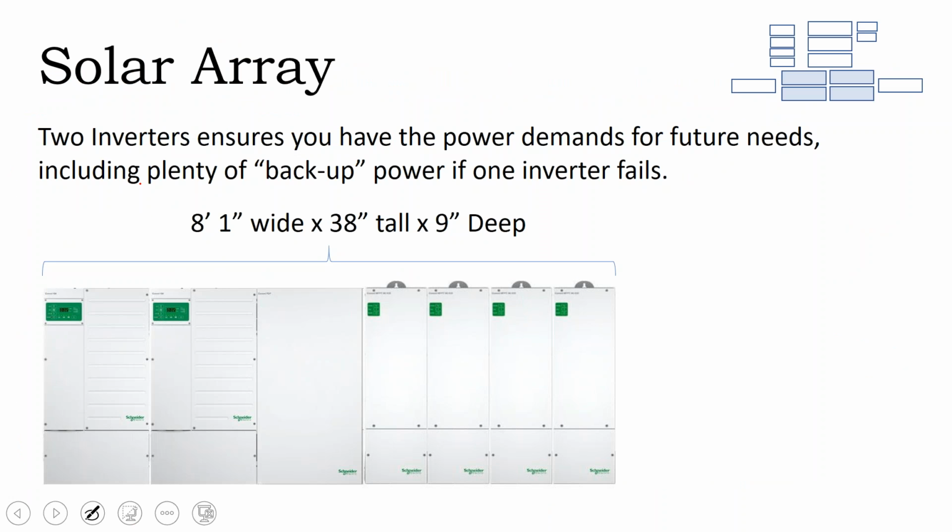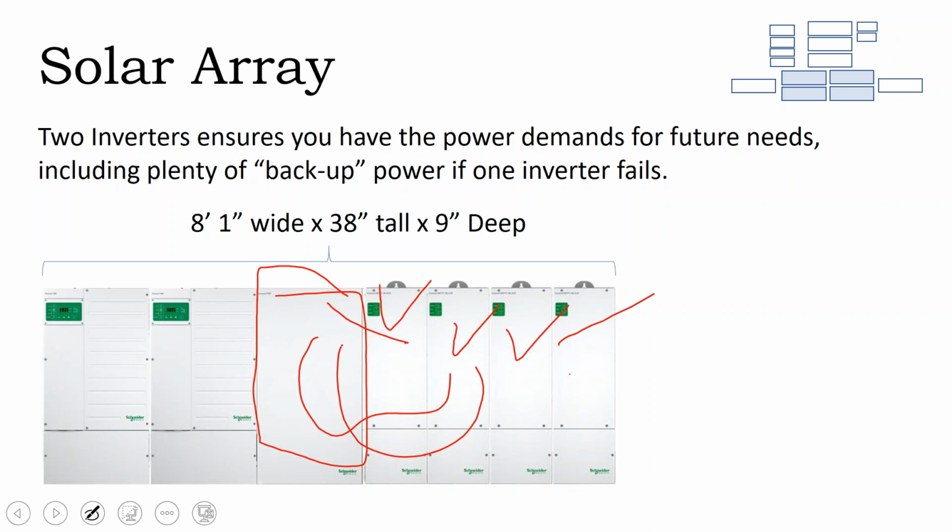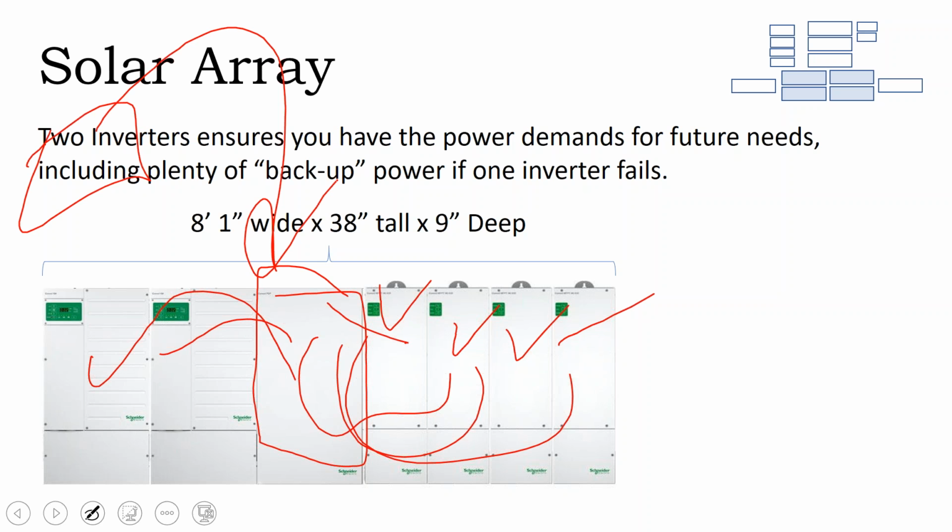This is our inverter system. And we have 4 charge controllers that are about 1 foot wide each, a little bit less than that. They're kind of like the batteries, about 10 inches. Then we have our electric service panel that everything is kind of wired into. And there's a DC side and an AC side, and the generator comes into that as well.